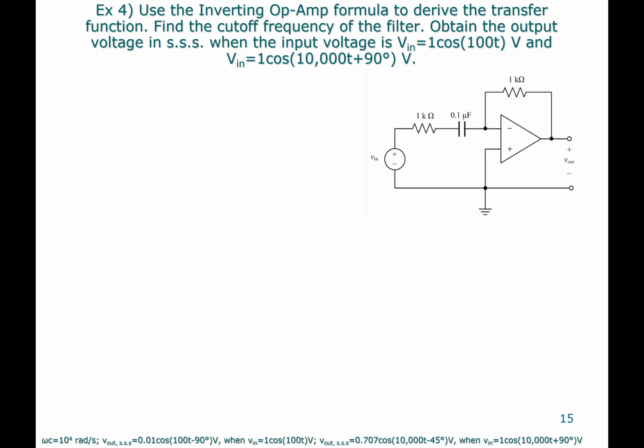You can also do these things with op amps. We're going to be playing around in the lab tomorrow with an op amp. This is considered an active filter, when you combine filtering with some amplification. Again, you have a 1 over j omega C. You have a feedback impedance, which in this case is just, we can call this R. You've got the same R over here. You can call this your source impedance, right? And this is an inverting op amp, right?